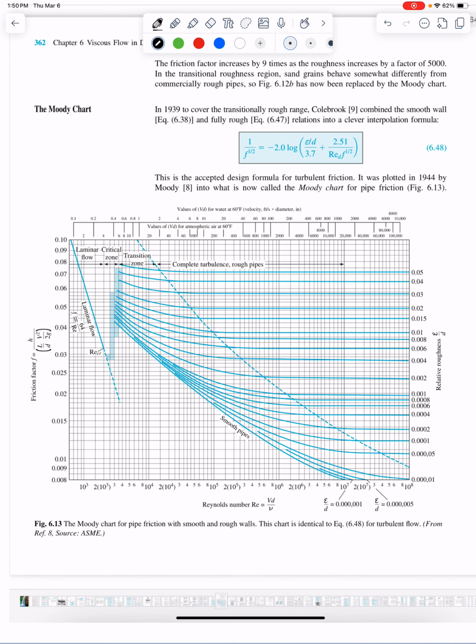All right. So in the Moody flow chart, here's what is important to discuss. If you look at the right-hand side, relative roughness refers to your pipe characteristics. That's how rough the interior of the pipe is, because how rough it is plays a role in the friction factor. Higher values mean a more rough surface inside the pipe, which refers to a higher friction factor. Lower values refer to lower friction. So that's that right-hand column.